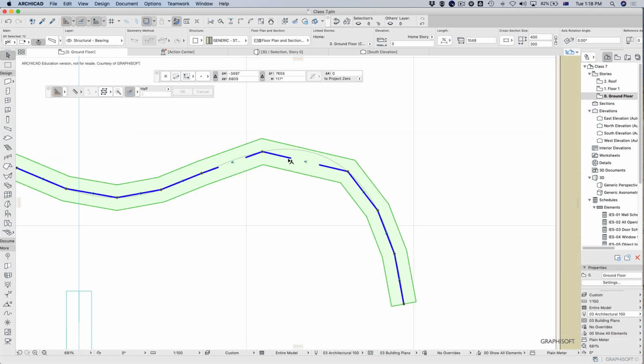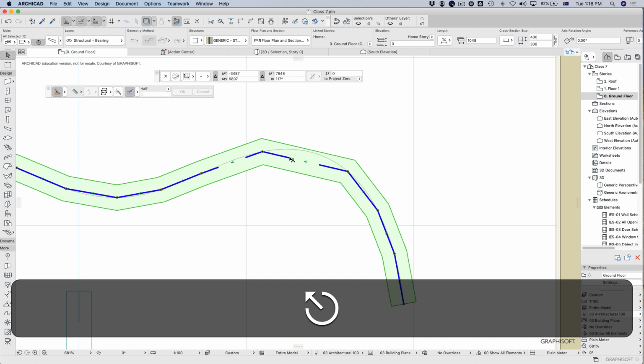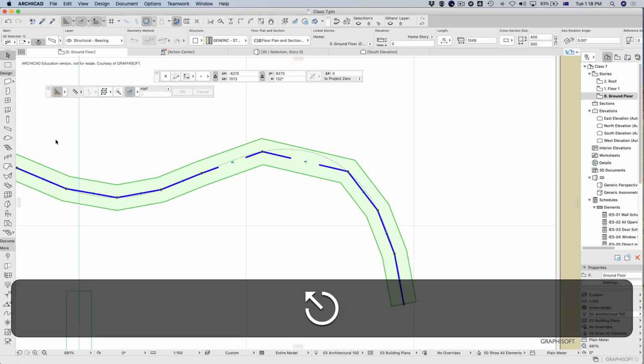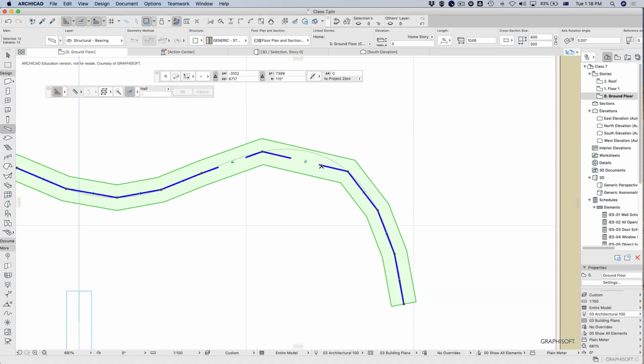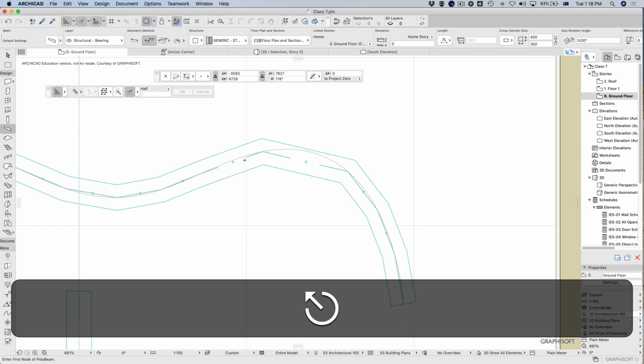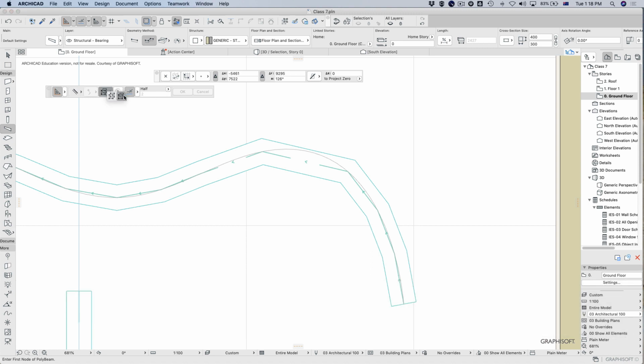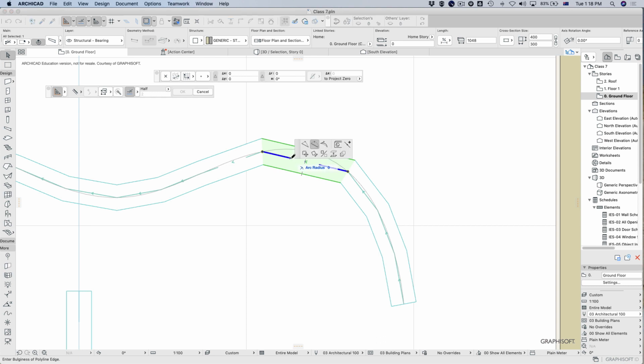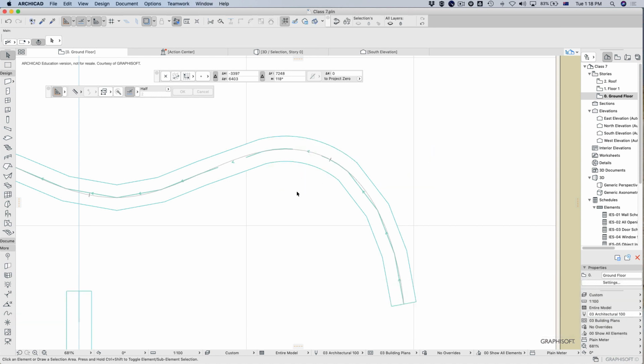Okay, and I can manually curve these as well, which is just showing you what the magic wand settings do. Okay, now see, this is a good example. See how I can't actually get to things? Even if I go back to here, I probably still can't do it. No. So what I have to do is suspend my groups. Now I can select this one individual beam, and I should be able to grab that individual beam, yep, and get it to snap to there. Okay, so that's what the magic wand tool is doing for you.